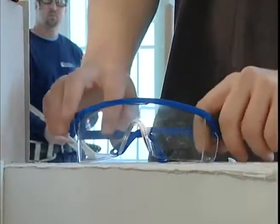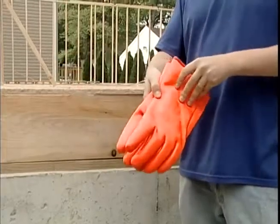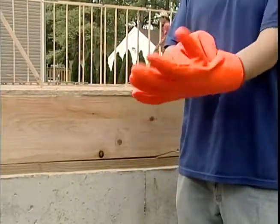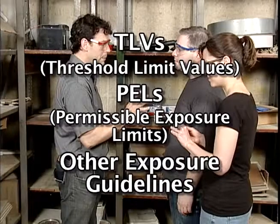For eye protection, you may be directed to wear safety glasses with side shields or safety goggles. To defend against skin contact, rubber gloves and other protective clothing might be recommended. Section 8 of the SDS will also list any TLVs, threshold limit values, PELs, permissible exposure limits, or other established exposure guidelines for the material or its hazardous ingredients. This information is used by your employer to determine the engineering controls and personal protection appropriate for the work you are doing.